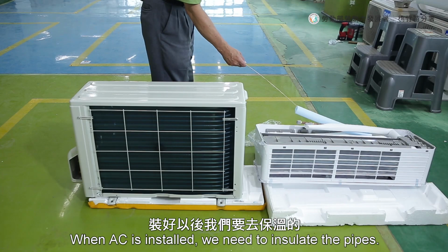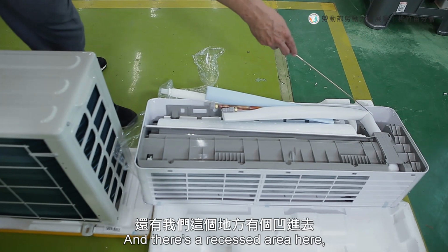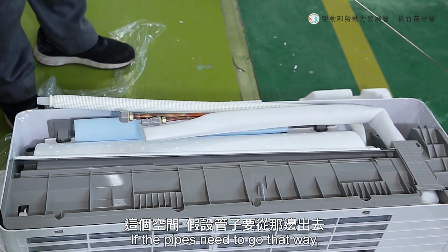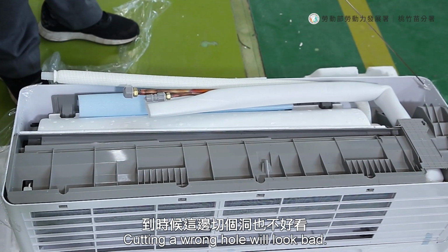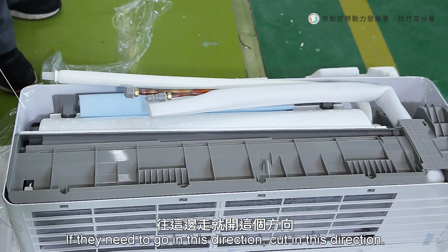When AC is installed, we need to insulate the pipes. We use it to insulate the connecting pipes, as well as for the drainage. And there's a recessed area here, so we can see some space here. If the pipes need to go that way, then we should cut it in that direction. Cutting a wrong hole will look bad. So if the pipes need to go that way, cut in that direction. If they need to go in this direction, cut in this direction.